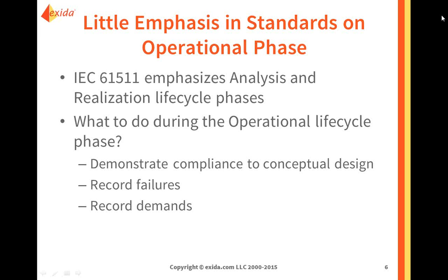As part of that design, we may have assumed certain equipment and certain levels of redundancy, but one of the parameters that we've assumed is a certain proof test interval. So we may have said, well, we need to test the sensors or transmitters once every 5 years. We need to test the logic solver once every 5 years, but maybe the valves once every year. But let's say we have a toxic gas detector. The toxic gas detector may only need to be proof tested once every 5 years, but it has a sensing module that needs to be replaced once every 3 months.